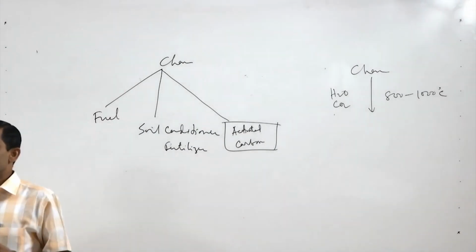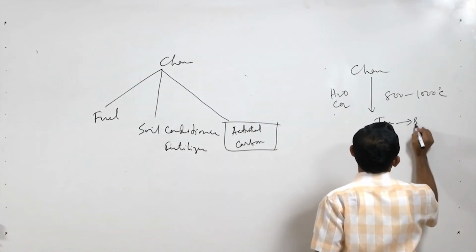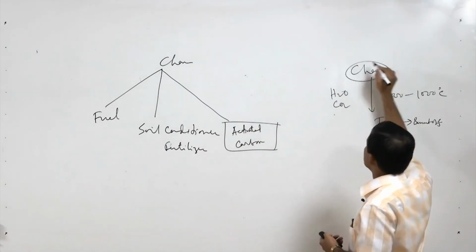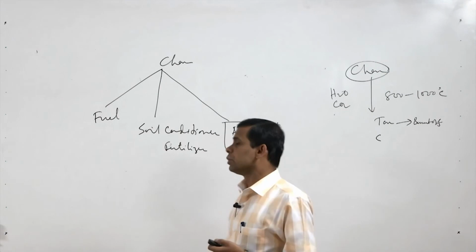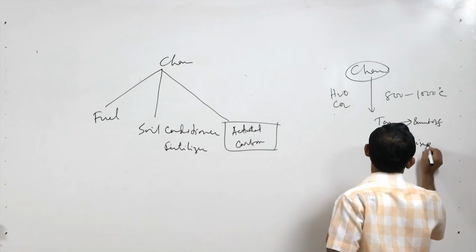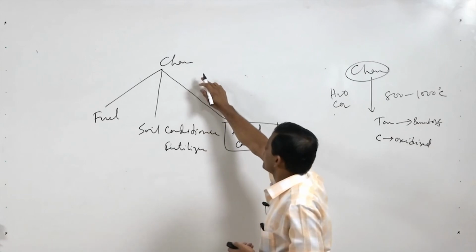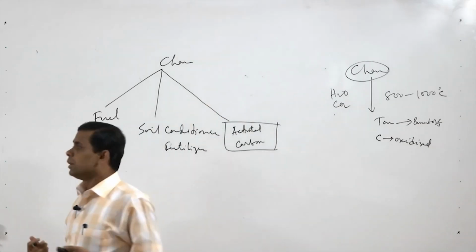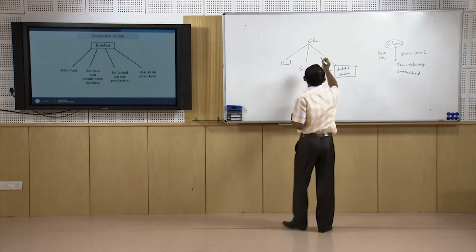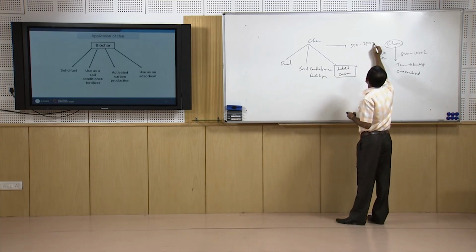Due to this, the tar present in it is burnt off and the carbon present in the char is also further oxidized. As a result, the skeleton of this char gets more porosity. So, by this physical method we can increase the porosity of this char, and a surface area of say 500 to 2500 square meter per gram can be achieved.